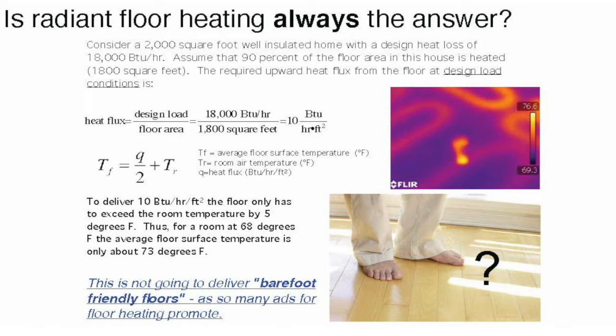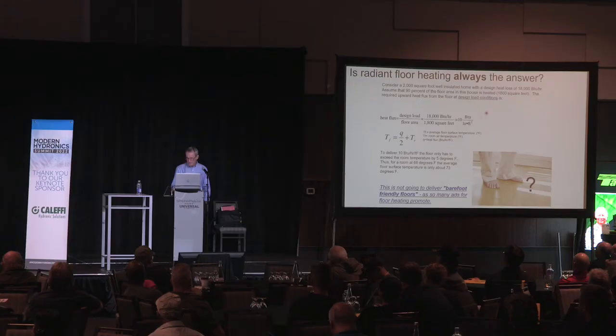Not that often cited 85 degree Fahrenheit that was more typical under design conditions in buildings that had 3 times the design heating load, okay? And again, I want to stress, it's not that the floor heating won't work, it will. Just don't overpromise your clients that you're going to have those warm, toasty floors. The floors will still be warmer than they would be with pure convective heating, but they may not be as warm as what that client might have experienced in an older building that had floor heating in it, okay?